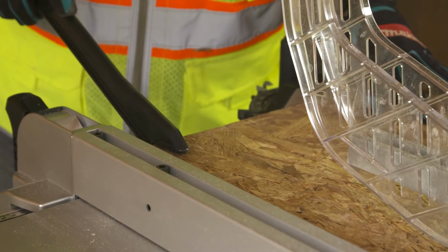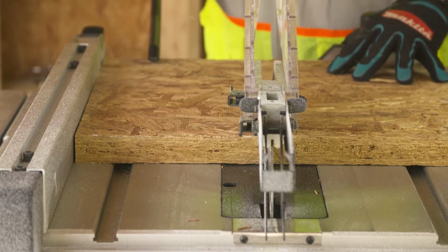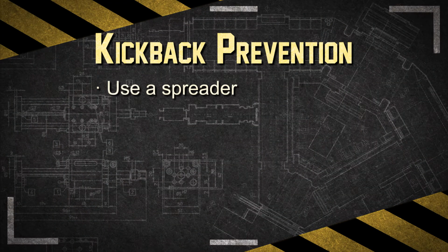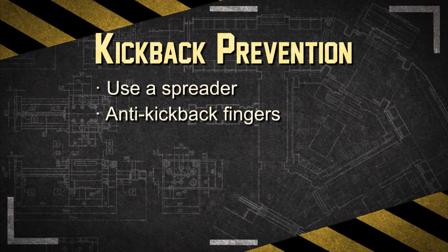Kickbacks occur when the saw blade catches during cutting and throws the material back toward the operator. In order to prevent kickbacks, use a spreader to prevent material from squeezing the saw or kicking back. Use anti-kickback fingers to hold the lumber down.